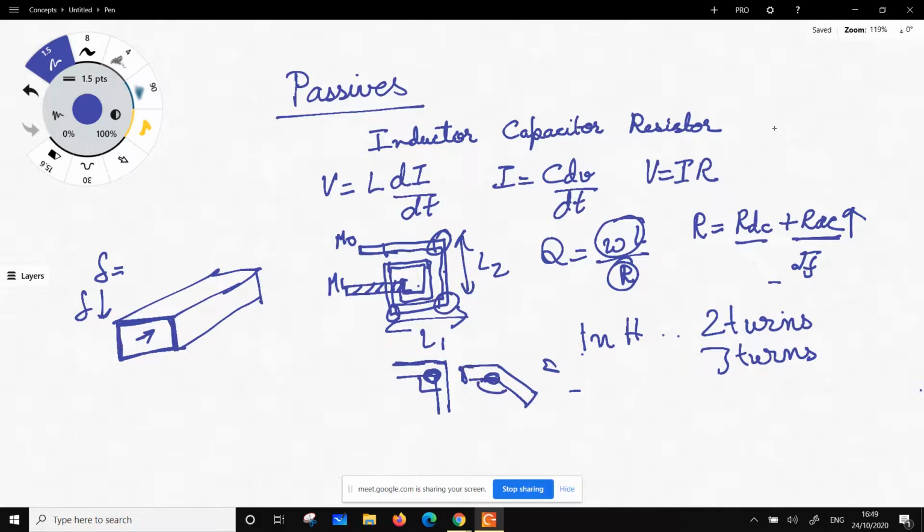So that means that if I was to do an octagonal inductor, do you think it is going to have a higher Q? The answer is no. The reason is, though the angle is more, the number of corners in a coil is also more. So all the advantage of increasing the angle is gone by introducing more corners. While if I was to do a spiral, this would be a best case scenario.